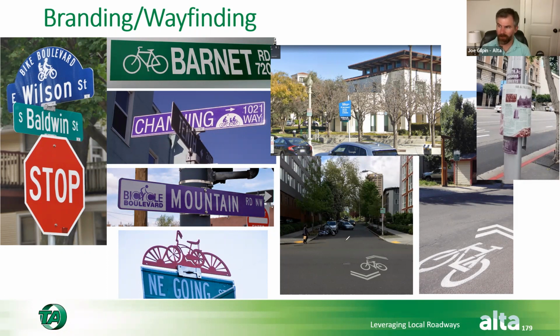And then markings themselves. I showed the image of Palo Alto and Berkeley that have the really big, full lane width bicycle boulevard pavement stencils. A lot of cities using just the shared lane markings are a little easier to use. This example is from Seattle, where they're showing one marking with arrows in both directions at corners. Sometimes if you have to take a turn, this one shows the arrows angling you towards an entrance to a Class 1 path right here. So it's kind of neat, the variety of things that you can do with some of this stuff.